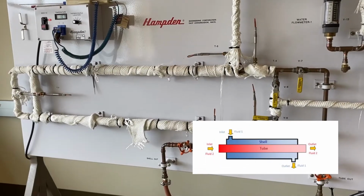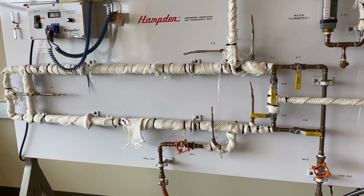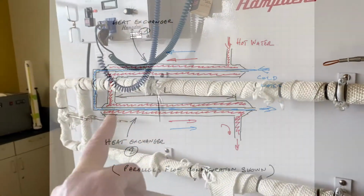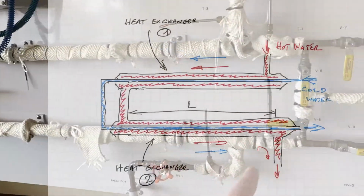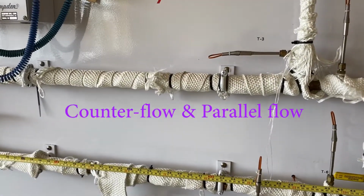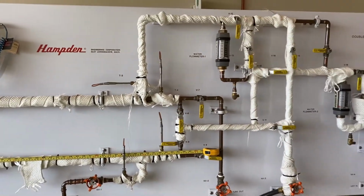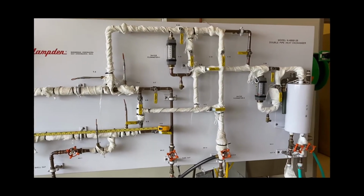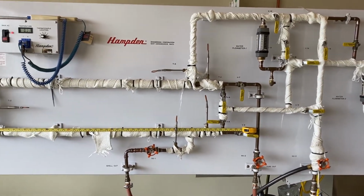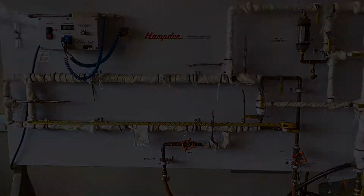That heat exchanger is made of two lengths of tube-in-shell heat exchangers. There's one length here, and the second length is here. Counter flow and parallel flow can be set up using those valves, so it's important to look at the diagram provided and find out how you can set up a parallel flow and how you can set up a counter flow.